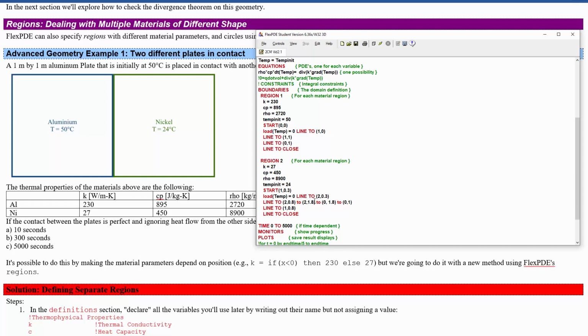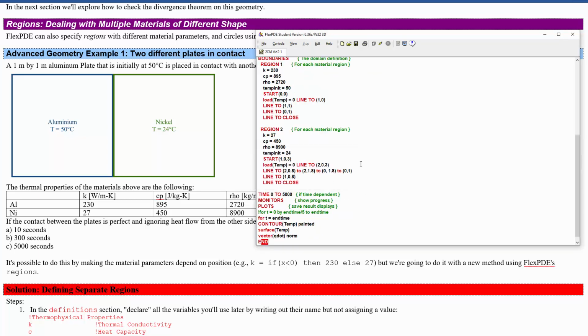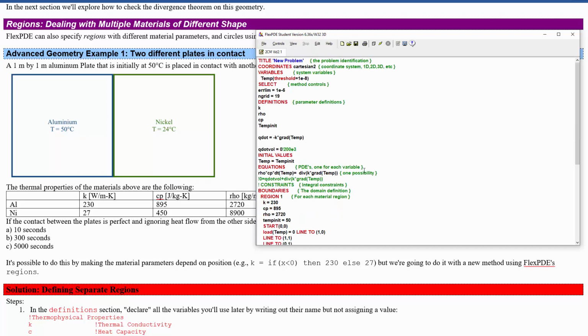And actually, this is going to cut through the side of the aluminum when we close it. Oh, doesn't like it. Too complicated. So let's go to, oh, actually, we can just lower the end grid. With the shape getting more complicated, 19 isn't going to cut it anymore.